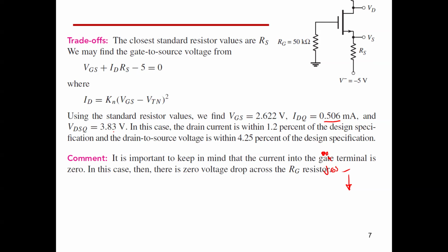However, in design, guys, it's not going to be very complicated like that. Why? Because simply you can control your VDD and VSS. So instead of having -5, I can change this value in order to reach the desired value of ID that I need. So your supply is going to control that. Okay, so this is a concept in the design.